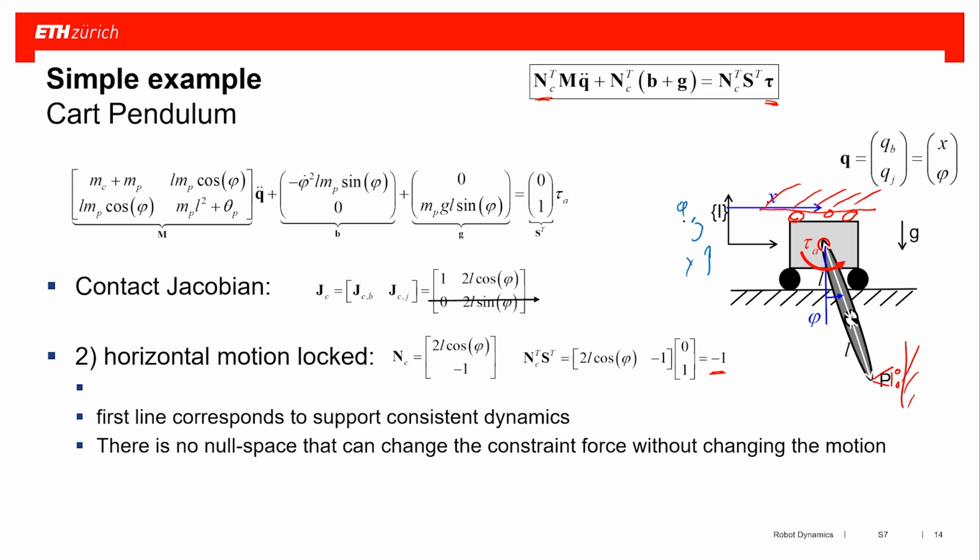So if we use the new Jacobian for floating-base systems, it seems that we have to put in 3D even if you have a planar system. This is not the case. A floating base in 2D means we have X and Y and one angle. That's the floating base. And then the actuated joints here are one link joint, this tau A around the phi axis. And that's the same for humanoids, arms, or quadrupeds, or whatever. So in 2D, the floating base description is with two positions and one angle.